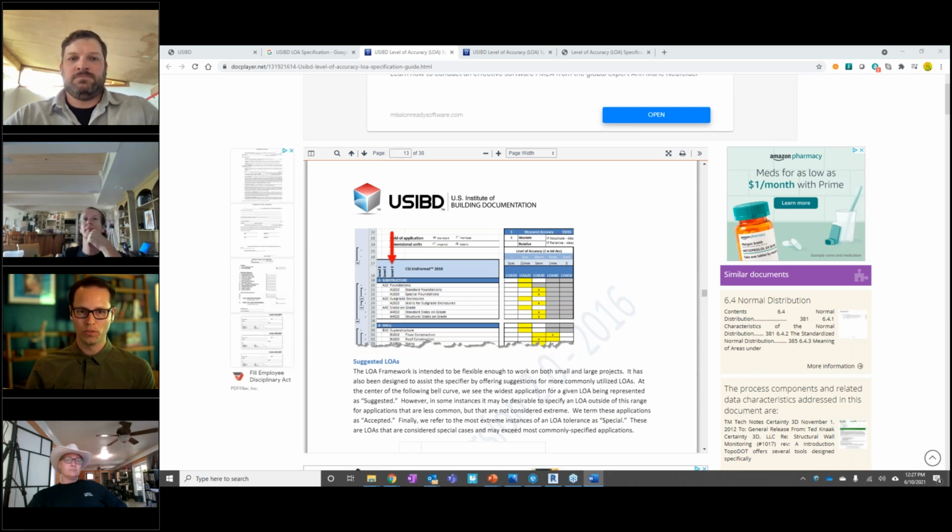using shared coordinates. 2 years from now, the client calls you and says, "Hey, Kelly, I just removed this point cloud." It happened to me. I removed this point cloud, and this was a project where we actually moved it manually for some reason. So I had to send him a list: load this level, move it 5 inches down, rotate it this many degrees. If you lose those translations, you're done.